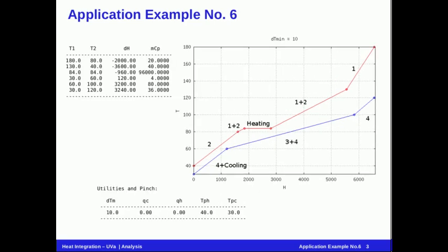And here, in order to introduce utility design using the composite curve diagram, you can see an example of heating and cooling. The minimum heating, 960, at the temperature 84 to 84. This is a flat stream. And the minimum cooling, 120 kilowatts, from 30 to 60 Celsius. That is not very normal. We will see utility design in much more detail. And this is all.